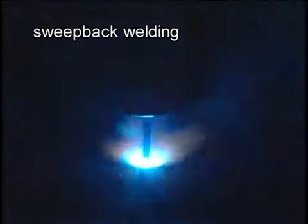In the sweep-back welding method, the molten weld metal is pushed into the center of the generated arc. This results in deeper penetration, narrower bead width, and convex weld reinforcement because the wire is being deposited onto the base metal directly.